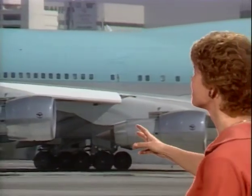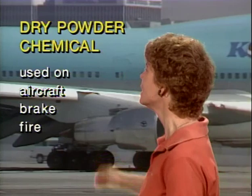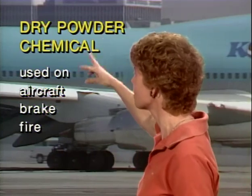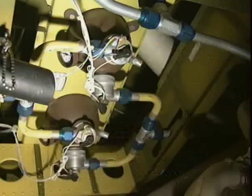Now, on large aircraft like this, it's not at all uncommon to have brake fires on the aircraft. And the appropriate extinguishing agent to use if you have an aircraft brake fire is dry powder chemical. Dry powder chemical is what you would want to use on a brake fire.